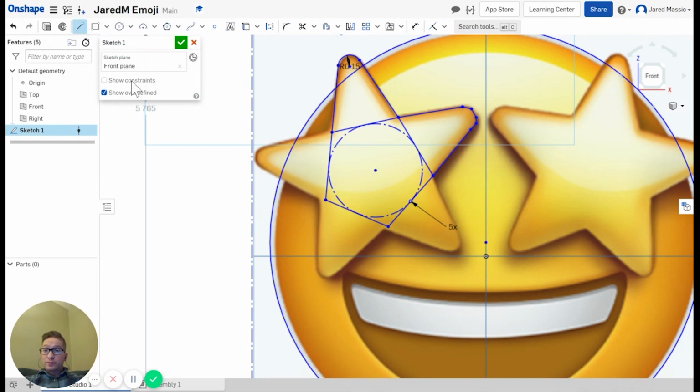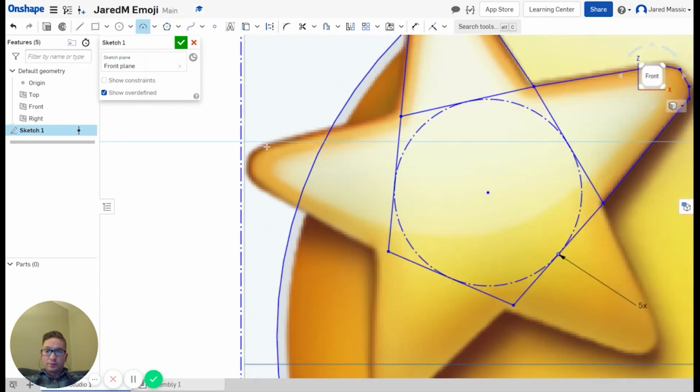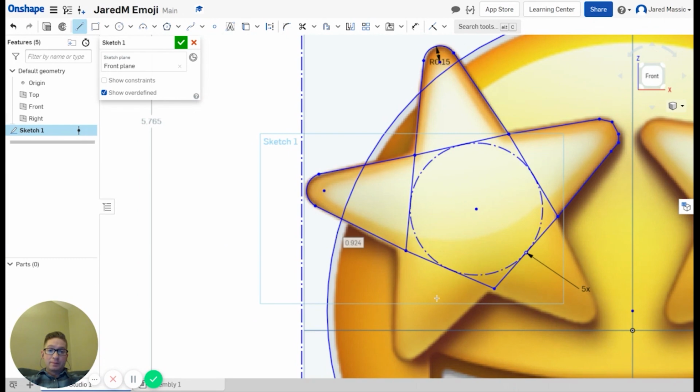The other thing you can do, if you have a little radius corner here, you can go to this 3-point arc tool. Click on that, zoom in, and I could approximately go from straight to across there, line up that arc, and then go back to my line tool and connect. They have to highlight to highlight, and then highlight to highlight. That one was less problematic, so we'll probably do that one for the rest of them because that was easy and fast.